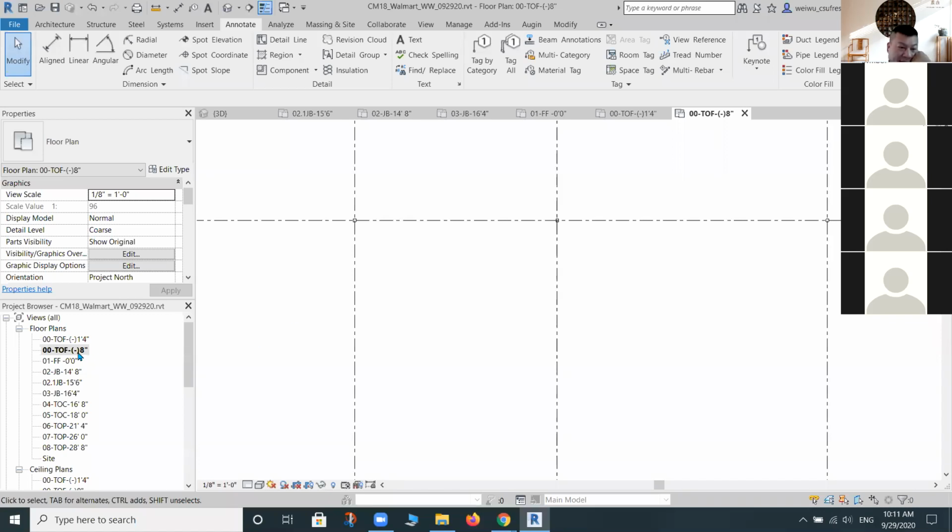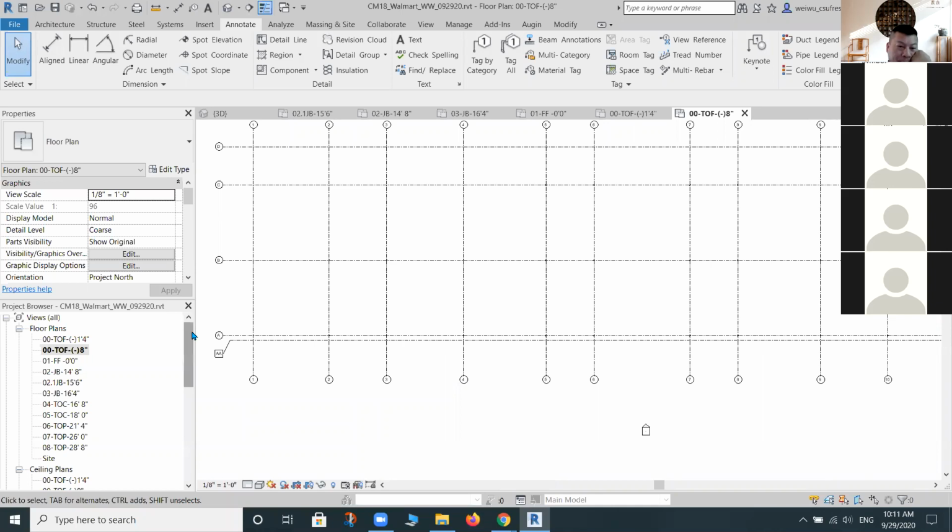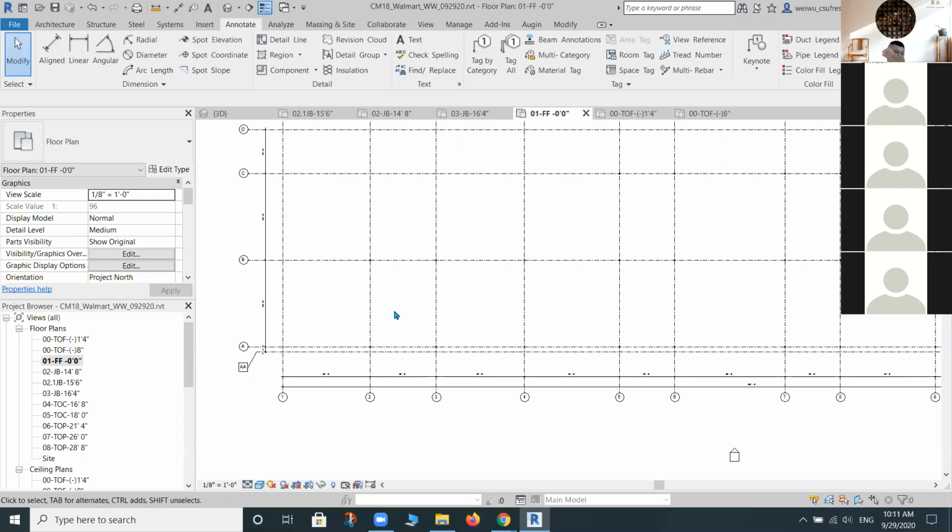And besides, I really don't want to place those column footings just by grid lines, which means that I don't want to place one footing per one column at one time. I want to do something that is easier for all of us, and it makes a lot of sense. In Revit, the reason they want us to place the columns first before placing column footings is because they embedded a rule that any column footing is supposed to be automatically attached to the bottom of the column itself, which means it doesn't matter which level you place those column footings.